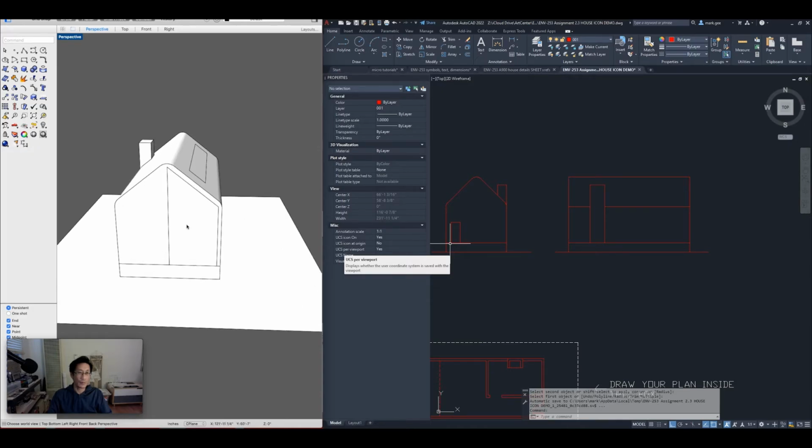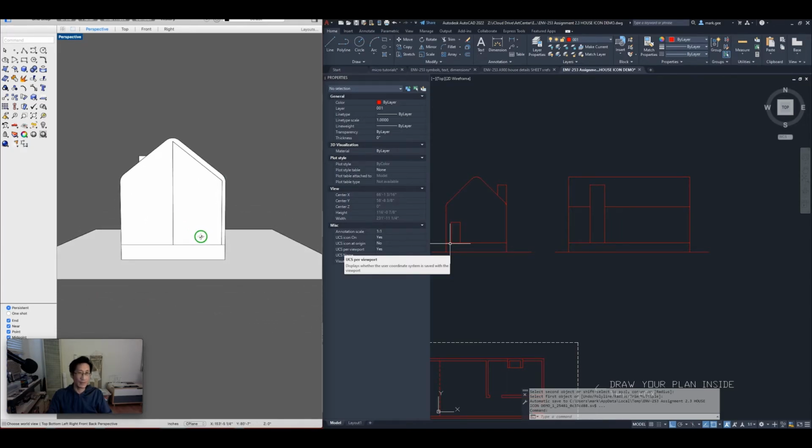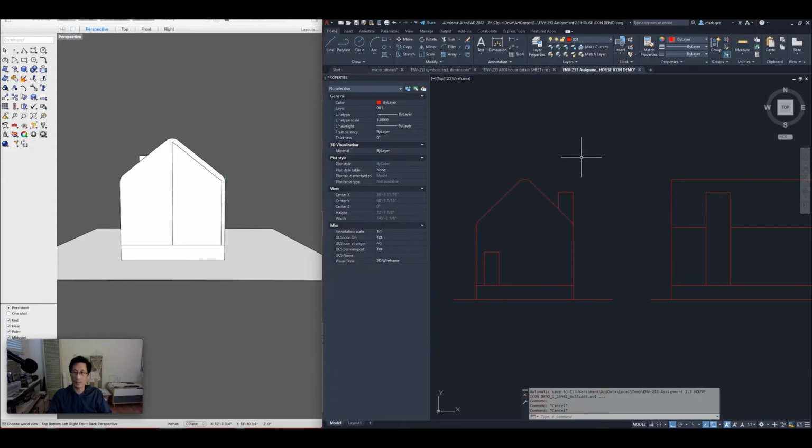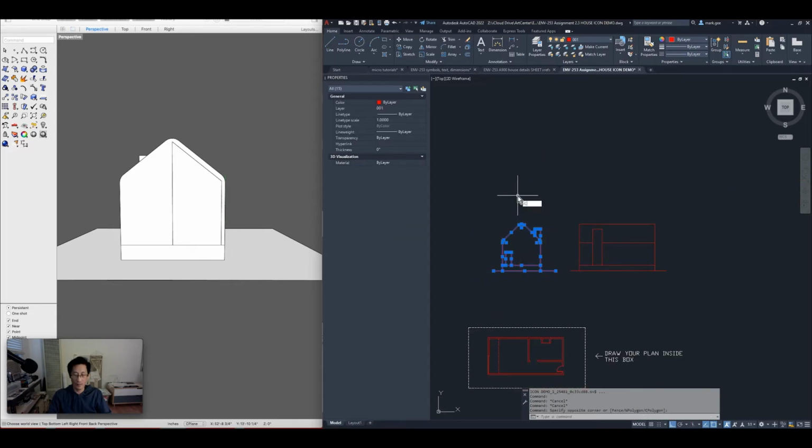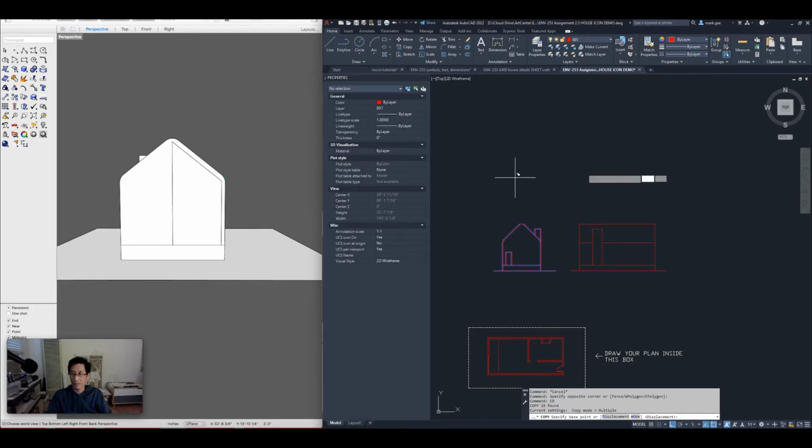And now we want to do this face. First of all, we know that it has the same outline as the front face. So let's just begin by copying that whole thing over. CO, and click, and I'll move it over, say here.